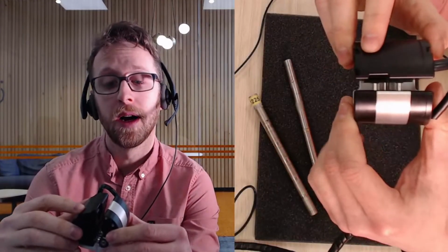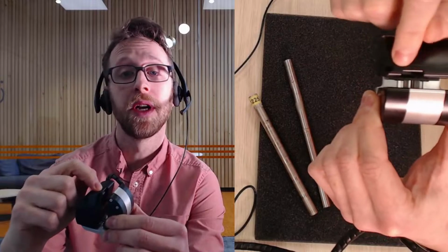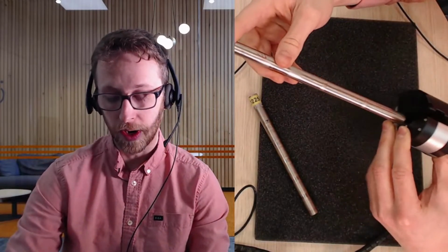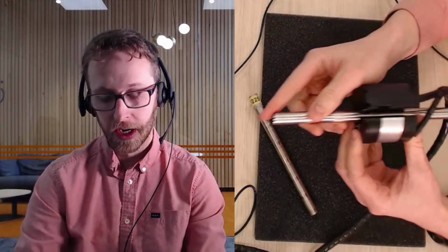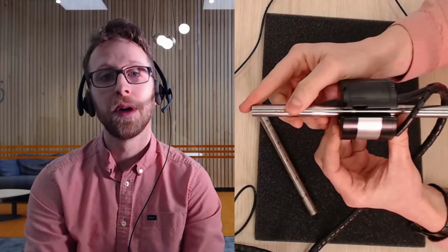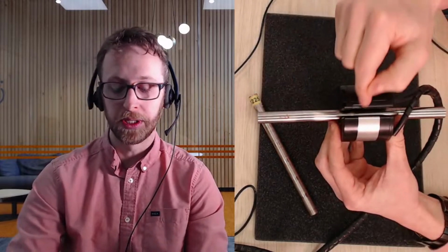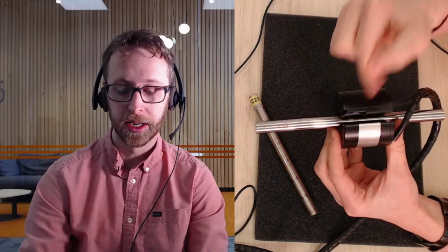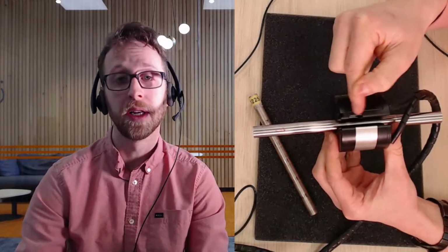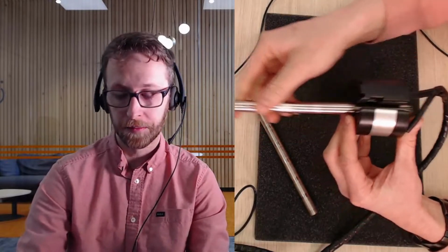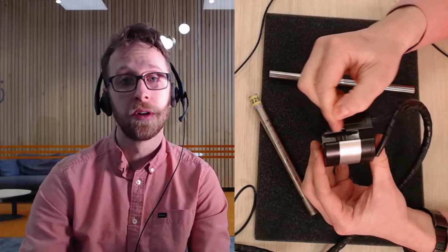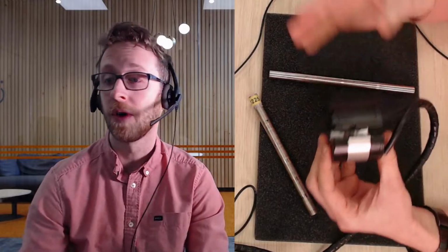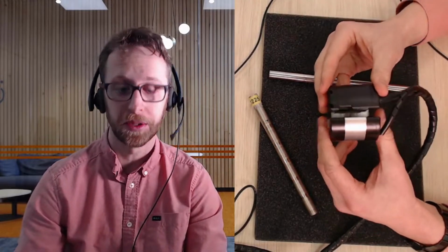On the top of the probe, you can see that there's a small window here. This is to allow you to see the weld center line. So if I place my sample here, as you close the probe, you will still be able to see the weld center line, and make sure that your weld center line is placed within that sensor area. It also shows you the coverage of the probe. The coverage of the probe for all probes is roughly 14 millimeters. So this is the inspection zone that you're looking for.